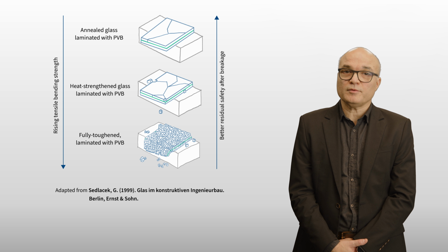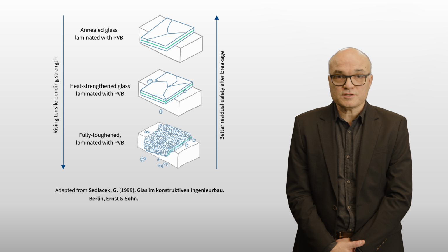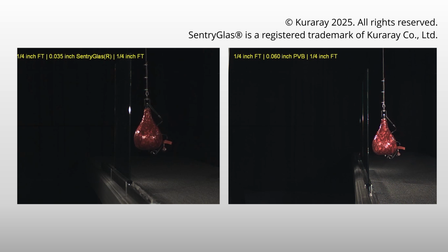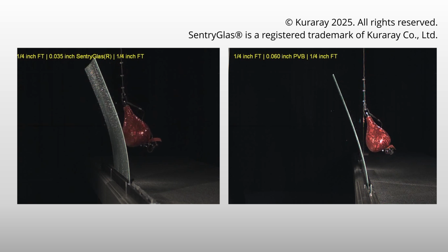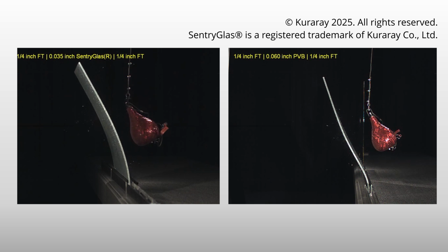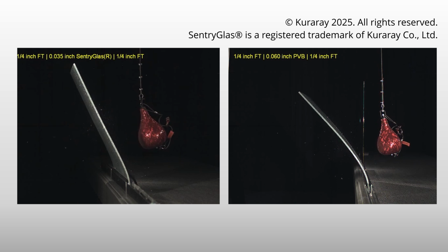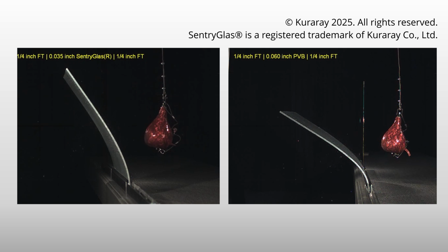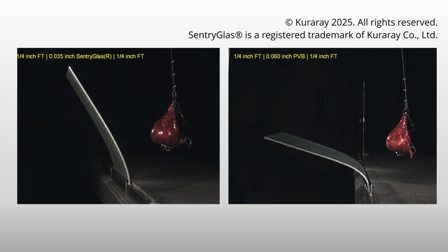The advantage of an interlayer is that it holds the glass fragments in place after breakage, which is important for avoiding human injury. But it also provides residual stiffening even after the glass has fractured. This is known as post-fracture resistance, which is an essential feature of some glass applications like balustrades, floor panels, and overhead glazing. Another advantage of laminated glass is thicker glass components than what can be produced directly from float glass, thereby enabling the accommodation of higher loads in bespoke structural applications.